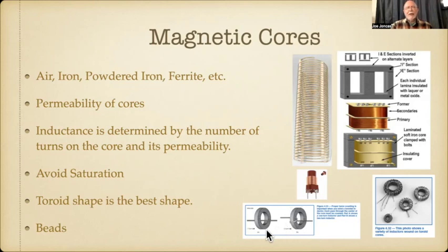In fact, most of your radios use these for the output, and the primary is probably just about 2 turns, and then the output has several turns like this. So it goes from a very low impedance to 50 ohms impedance. And they're not shaped like this either. And I wish I had one of those.